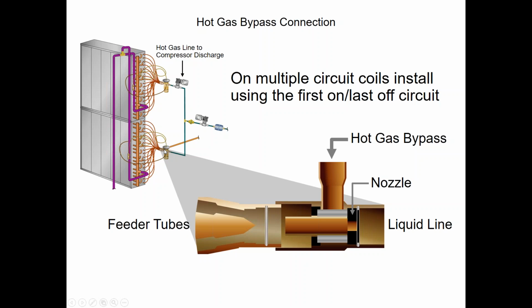We start really dropping the suction down. We could start freezing, frosting. We could start flooding back, all kinds of problems. So again, VAV and VVT never have phase split. Typically, phase split is more of a process application than a comfort cooling type application, okay? So hopefully that cleared that up a bit.